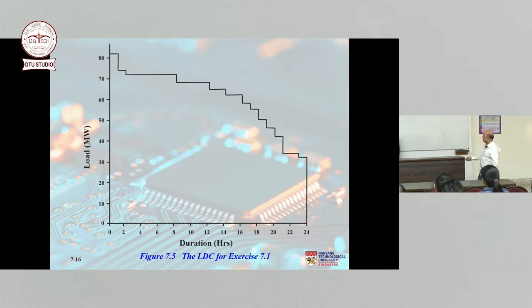Yeah. And if your load is 82 and the installed capacity is 100, so you are somewhere here, right? So if one generator goes out, 25 megawatt, you only have 75. You're going to lose load, correct? So how many hours are you going to lose load? You can just go here, you'll find it is 1 hour or 2 hours. And then you do LOLE is equal to the sum of P_k times T_k. That's it, very simple. I've given you the answer.